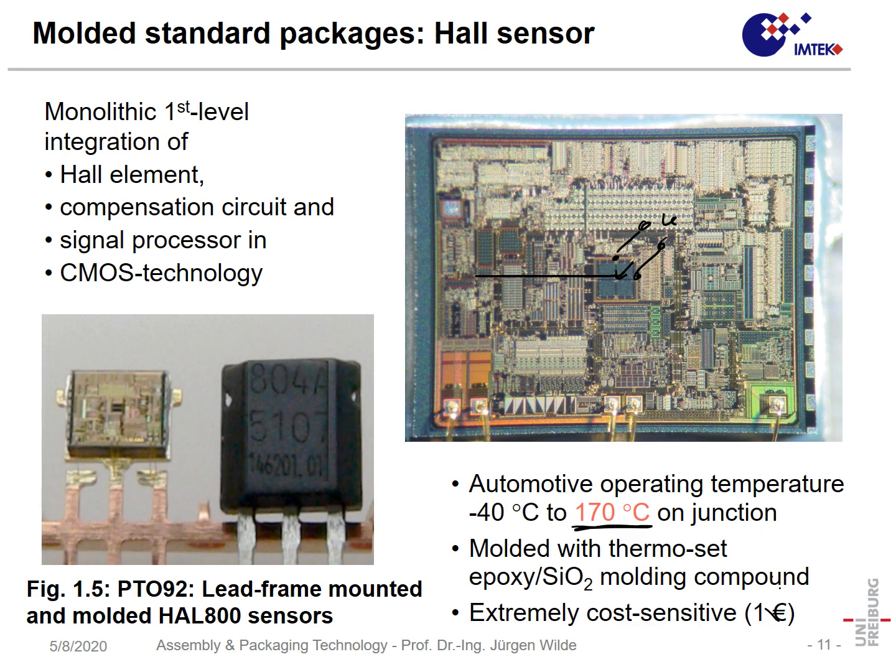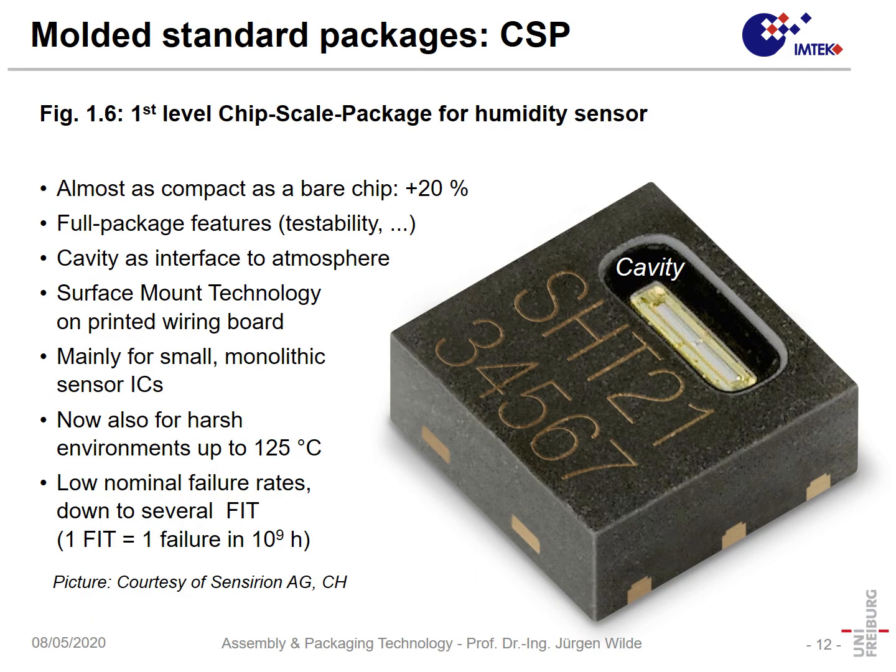Such a device is made on a lead frame. That's such a copper structure here. The chip is mounted. What we can see not so good is it is wire bonded, and finally it is encapsulated with a polymer material. And such a device is very cost sensitive. Also, it is very complex. The costs are significantly below €1 or $1 per device. I would say we are significantly below such costs.